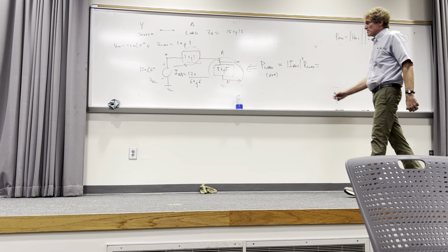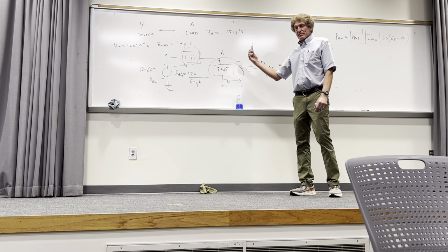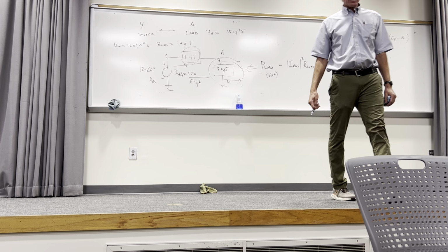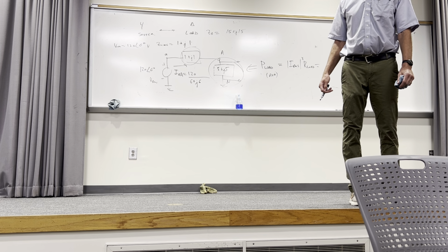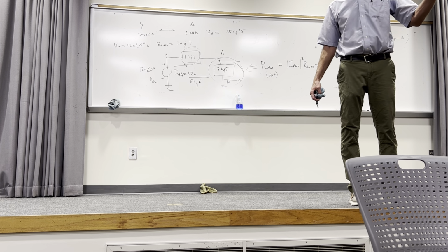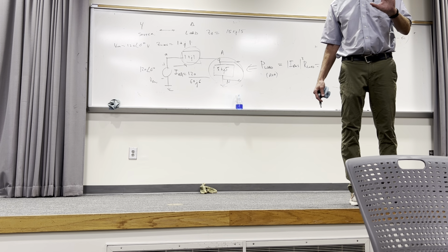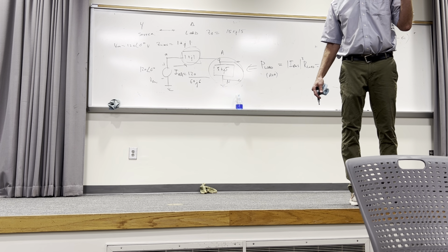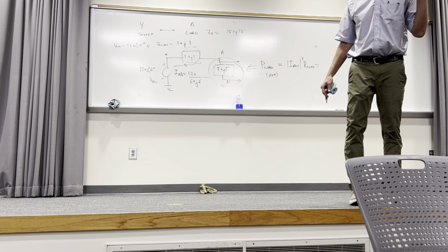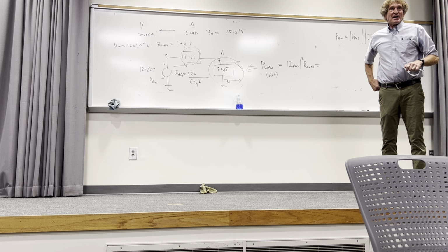But if you wanted complex power, it would be what? Take the actual polar form of VRMS, take the voltage here, that is the current times that load, right? And then you have to conjugate it. You would take the voltage developed there first, then you would take the current and conjugate it, and multiply the two together, and you would get the complex power. Are you with me? I'm not trying to insult you. I'm trying to just be as clear as I possibly can. Sometimes I don't know the best way to do this.